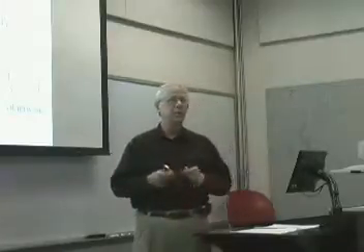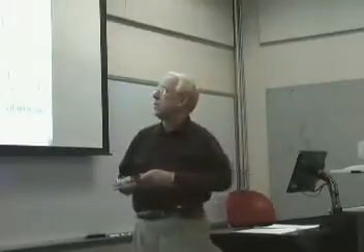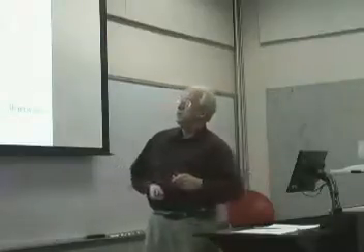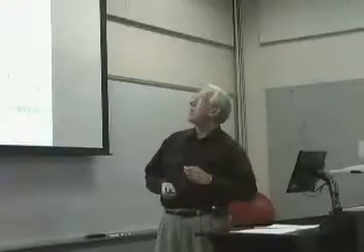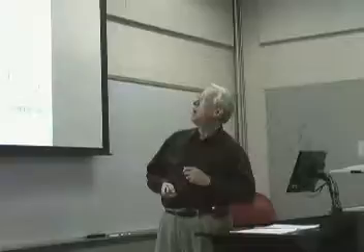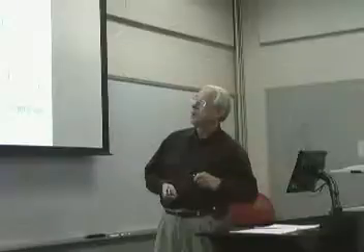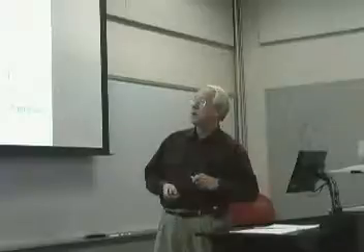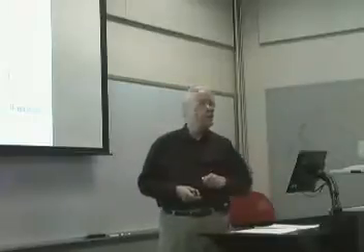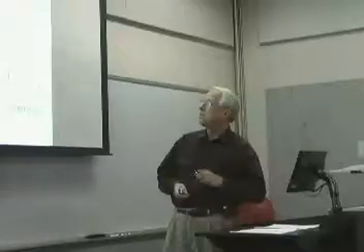This is what happens. It is not difficult. It looks overbearing here until you see how it works, and then you go, oh, that's not difficult. Here's the equation, so here's the residual times a weight, and I'm going to integrate that. And when I integrate that, then I'm going to say, aha, what I will get will be equal to 0 here. So wherever I have a temperature in here, I'm going to expand this as the product of what we call a shape function, and then the nodal value. That's why you have the T's here with the subscripts. So this is a shape function, and this is the nodal value.